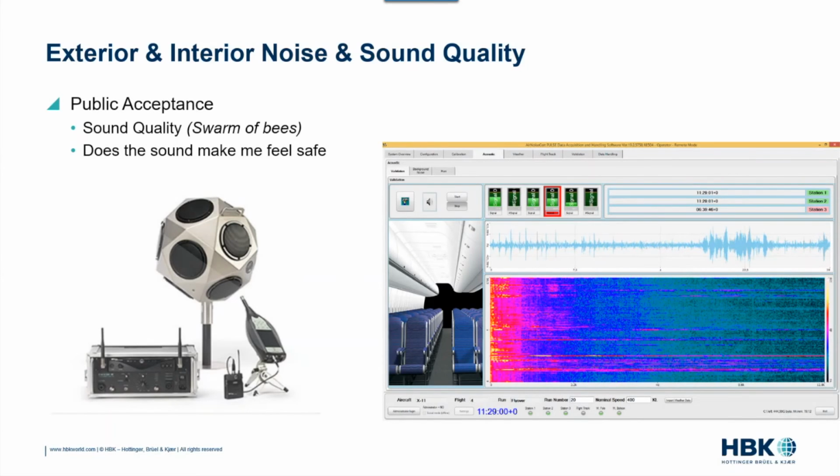Some people may say, oh, well, it could be perfectly quiet. Well, does the public want perfectly quiet? It's really nice for me to be outside and I can hear a helicopter coming from a long distance, so I know it's there. These eVTOLs have to be quieter than a helicopter, but I still think they need to have some type of acoustic signature so we know they're here, because they are going to be flying very low level, and the quantity of them is going to be a lot greater than what we're used to.